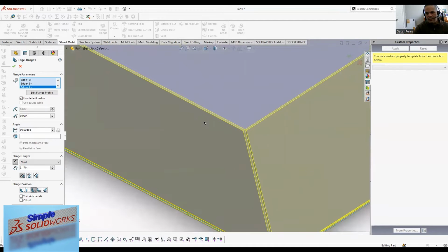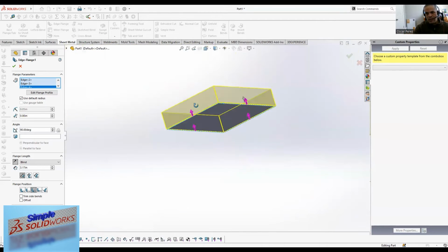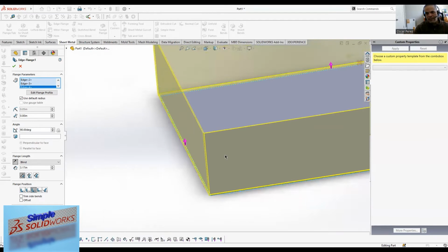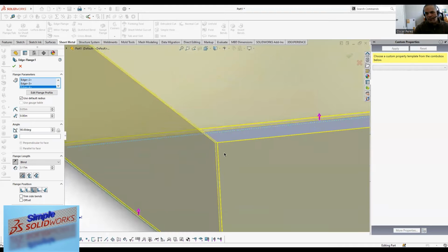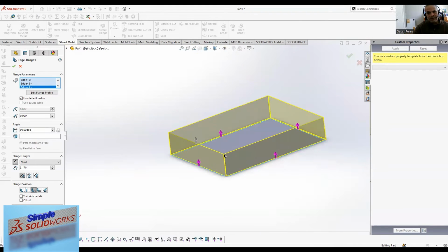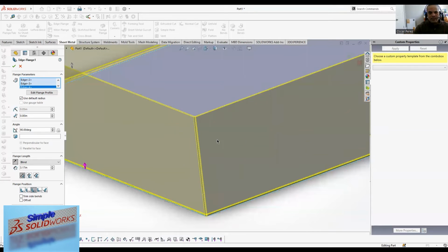See, it's all been sealed. Now, if you work in a place where they actually weld these things together, using basic welding technique, then you probably want to give it a gap, because that welder's going to appreciate that. He's going to really like the fact that you left enough of a space for him to put his rod in there. But if you have a place where they do automatic, laser welding, then take away that gap, right?